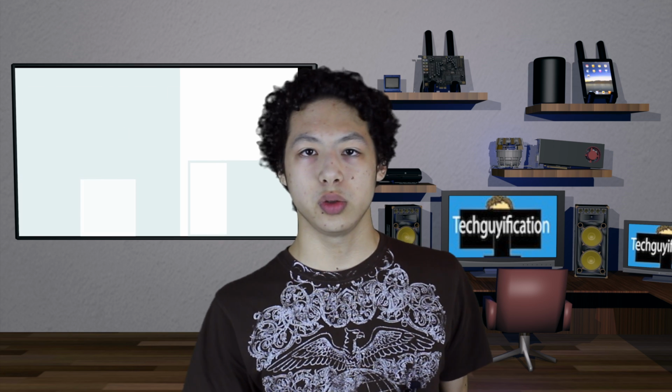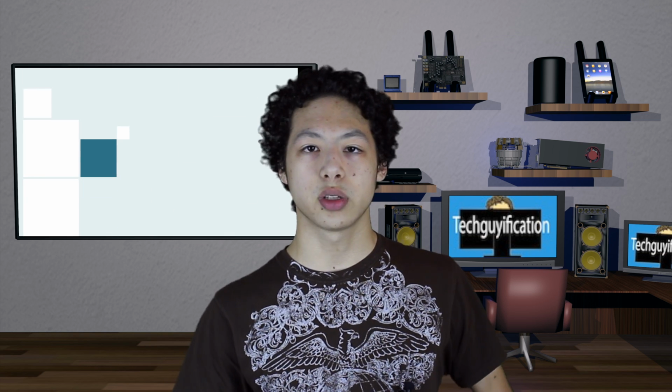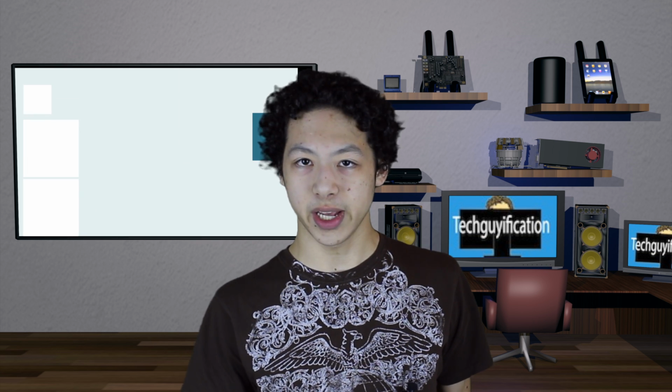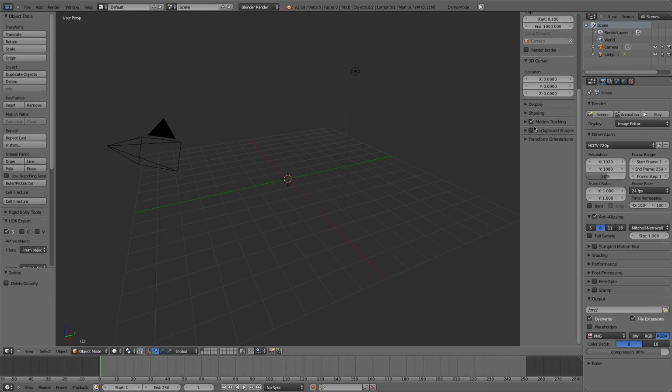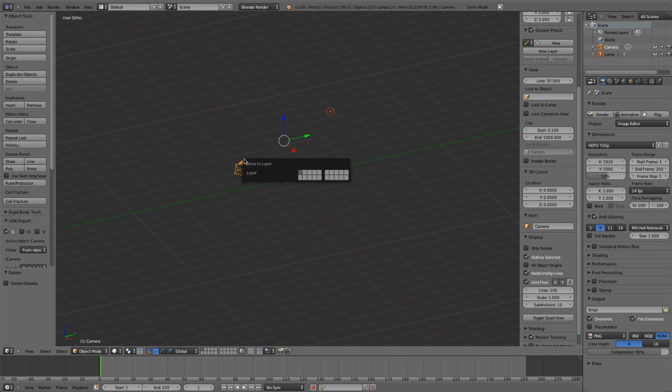After that, we're going to hit N to open up the properties panel if it isn't open already, and scroll down to where it says 3D cursor and set all three values to 0. Next, scroll down in that panel to where it says display and change the grid lines to 100. Now right click on the camera and then hold down shift and right click on the lights and press M and then move them to the last layer, which is layer 20.